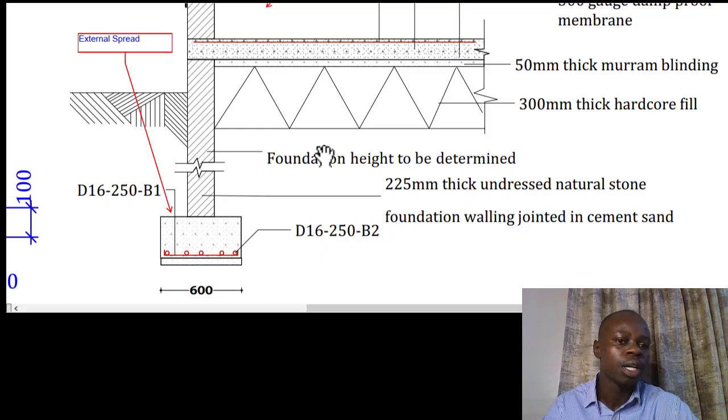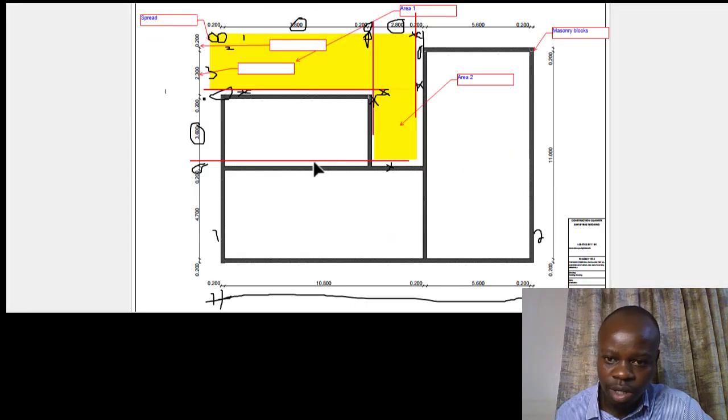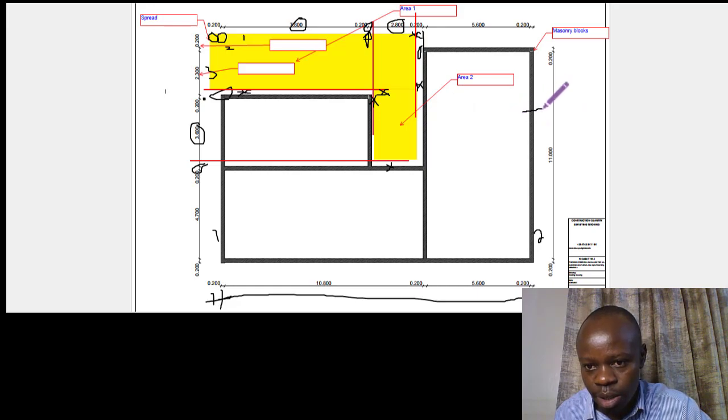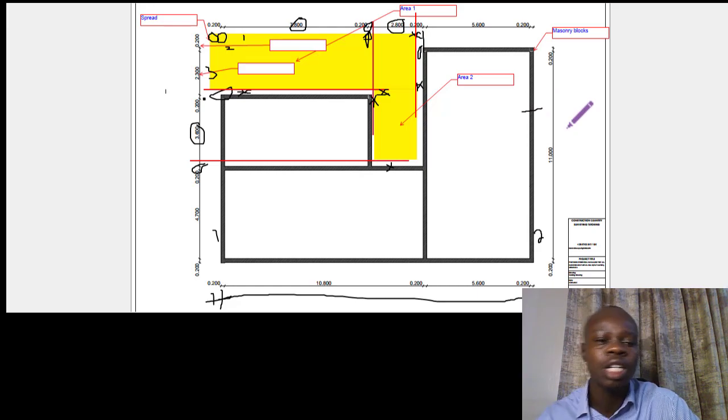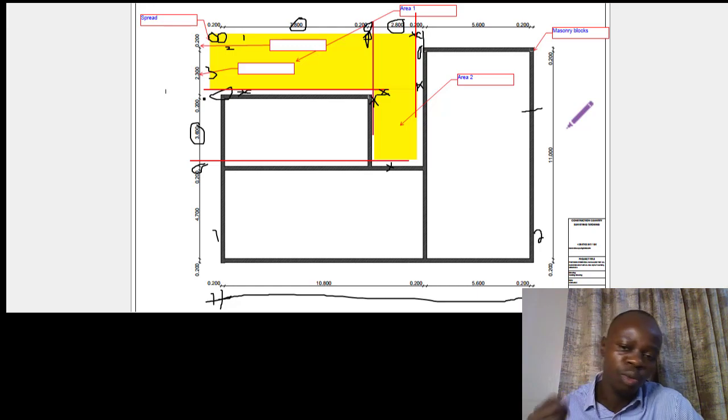The trench has been cut through. For instance, in this one, this is a plan to mean that it has been done above the ground surface. But below the ground surface is what we have been shown on the plan. So assuming that you would cut this particular plan, for instance, at that particular part, but below the ground surface, that is what you'll see from the trench section that we've been shown.